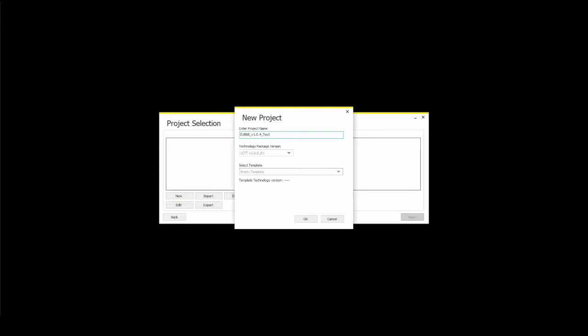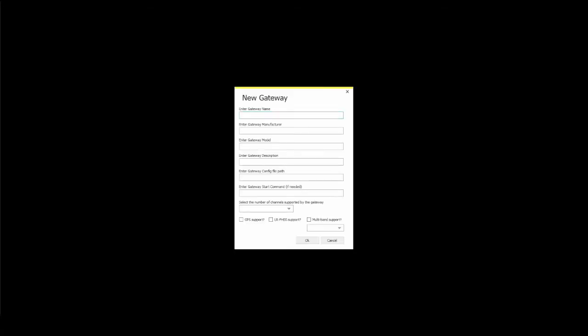The first step after creating this project is to assign a gateway. If your gateway is not listed by the LCTT yet, you could create a new one. In this case, we will create a new IMST Lite gateway and we will enter its information in the corresponding fields. If you are interested in the remote configuration of the gateway, it's important to enter the file path to copy the configuration file for the LoRa packet forwarder and also the command to start it.